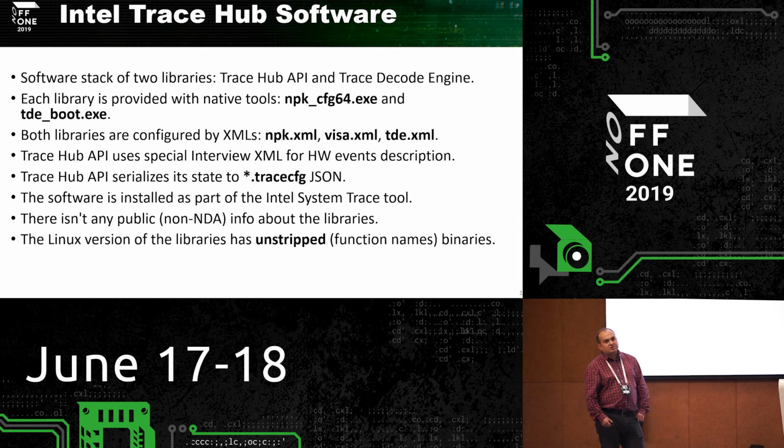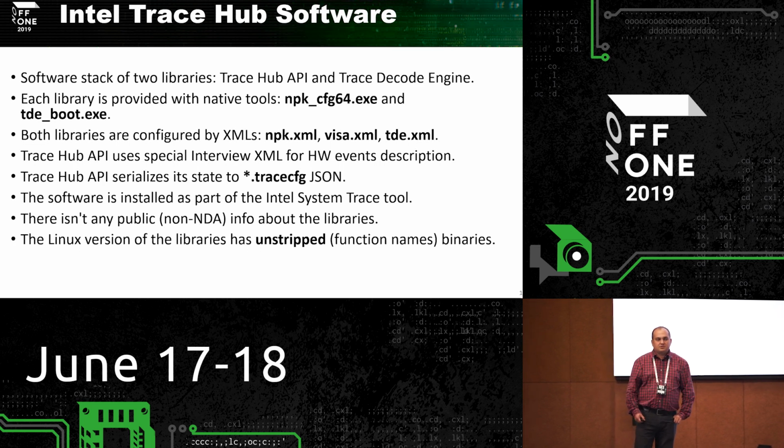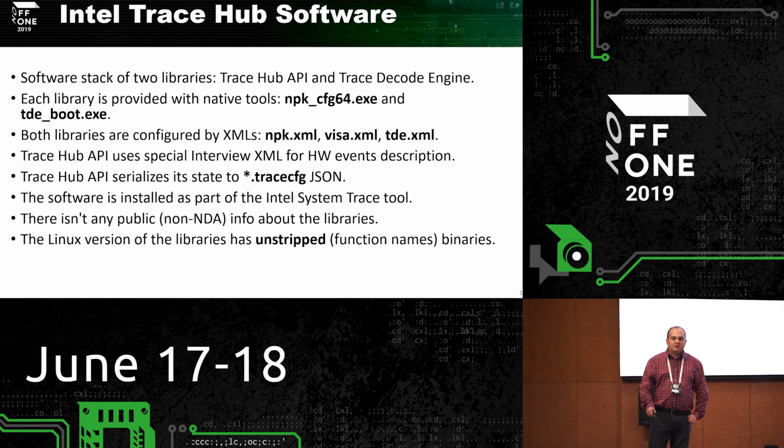Although they are part of the package Intel System Trace tool, it's quite a convenient utility, has a GUI interface written in Java, enabling one to get tracing messages from the BIOS files. And for ME, you can also get messaging, but this utility is based on the TraceHub API and the Trace Decode Engine. They are the foundation of all the tracing on the Intel platform.